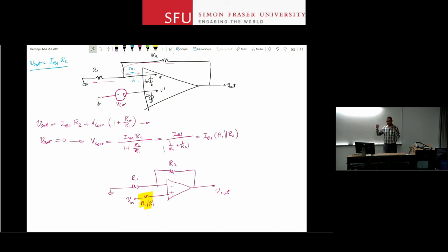So even if you have a 1 gigohm feedback resistor, a 1 femtoamp current gives you 1 microvolt of voltage drop across it. The noise from that resistor is larger than that. So if you're really put in a corner, go and choose a different op-amp. And if that's not possible, if you're doing something at home, something hobby, and you don't want to wait for the component to arrive, here is a solution that you can use to compensate for I_B issues.